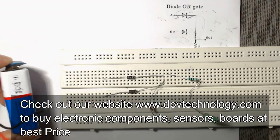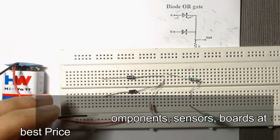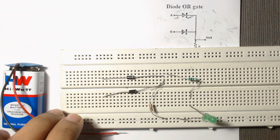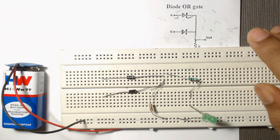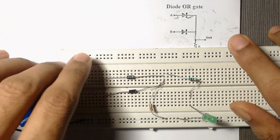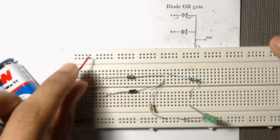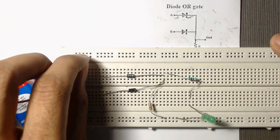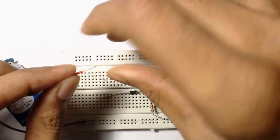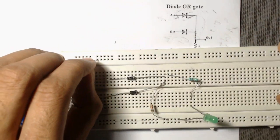Now we have to connect our battery. We will connect the negative terminal of our battery to this row because we have considered this row as the ground row, and we will connect the positive terminal of this battery to this row, and we will use this row as VCC. That means from here we will take out the signal 1.